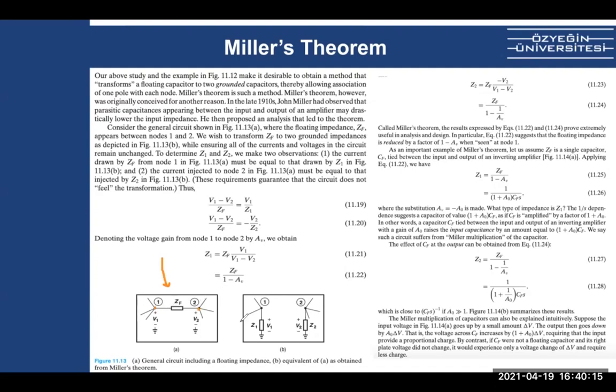And we want to make this one cap connected here, the other cap connected here, and we disconnect. So it's a simple nodal analysis. What he says is, well, there's a current going here. So if we make the circuit such that the same current goes here, the rest of the circuit is not affected, right? Because you are not really touching anything in the rest. You're just directing this current, instead of through the impedance here, you're saying it goes here. Same with node 2.